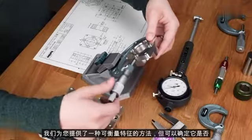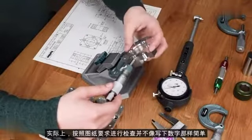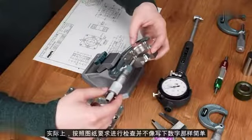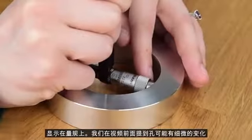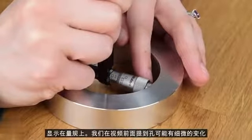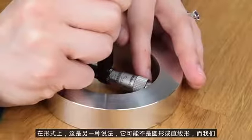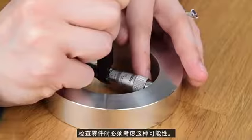We've given you a few ways that a feature can be measured, but determining if it's actually in spec per the drawing requirements isn't as easy as just writing down the number displayed on the gauge. We mentioned earlier in the video that a hole may have subtle variations in form, which is another way of saying that it might not be round or straight, and we have to consider this possibility when inspecting parts.